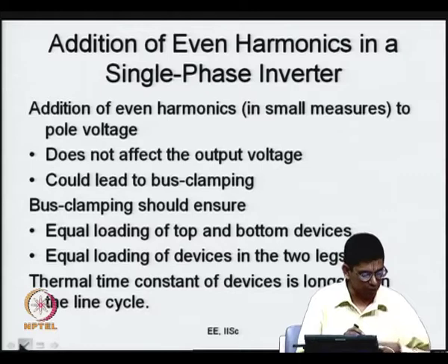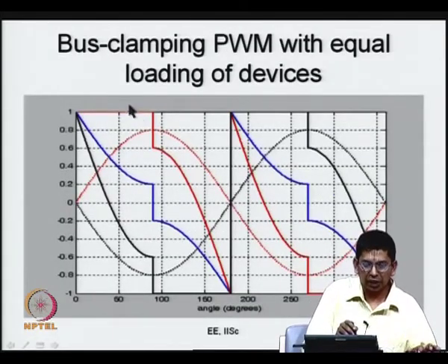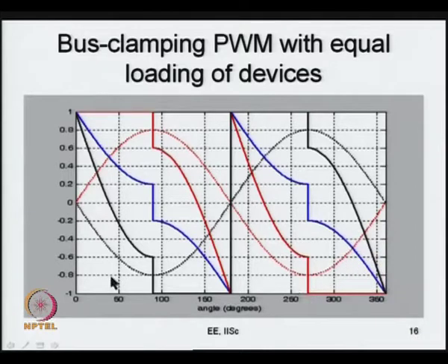You go forward. Here one device is conducting, and here another device is conducting. Because it is conducting, there is a certain amount of loss, heat is being dissipated, and this heat is going to increase the temperature, but there is a delay in the junction temperature rise. The junction temperature has some safe maximum value. When the device conducts, or because of switching action, the device dissipates energy.